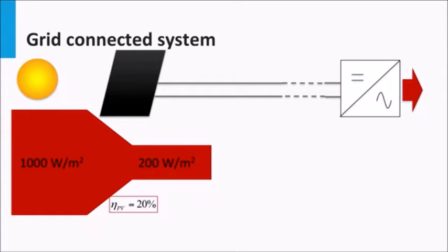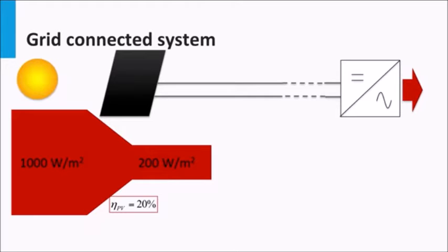As the balance of system could be placed at a considerable distance from the PV array due to the fact that inverters need to be well protected, it might be that the DC power loss in the cables is significant. Depending on the length of the cables and the amount of current through them, this loss could be anywhere around 1 to 5%.